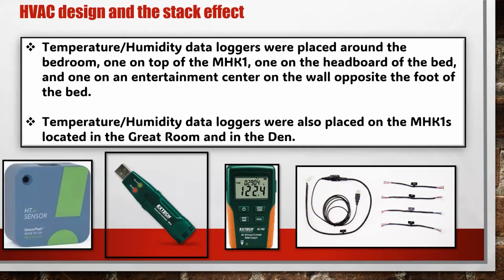And I like this one, individual zone comfort. That does not mean it simultaneously heats and cools. We just need to get better at designing these systems to not exaggerate the heating of the upstairs level. So we generally don't get overheating complaints on single level homes unless the units are drastically oversized.